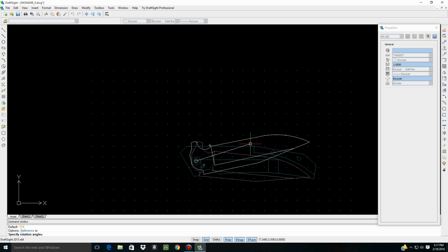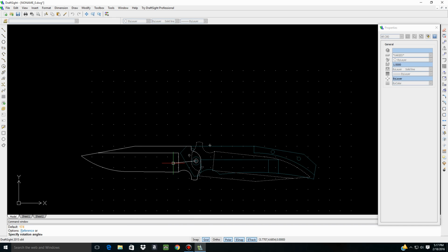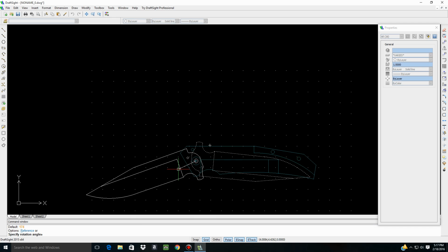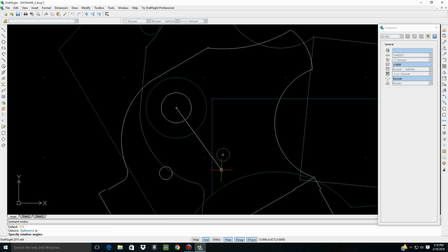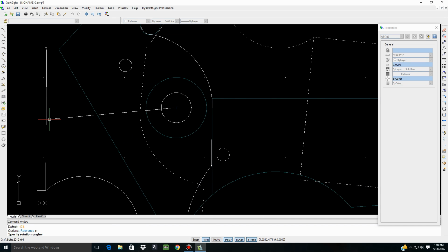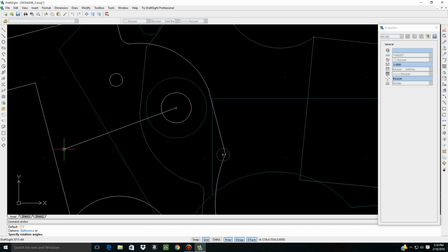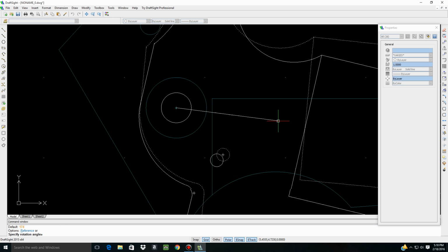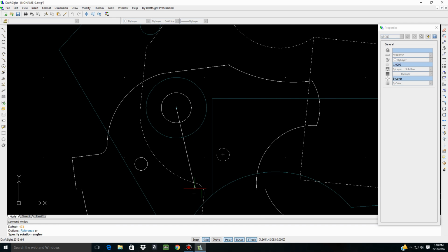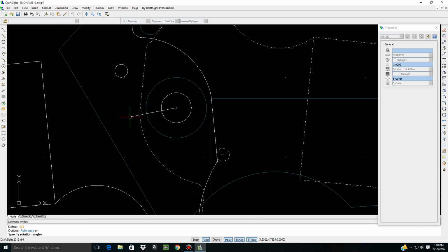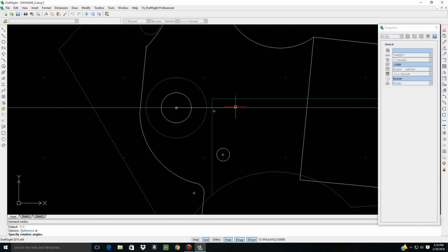You see, we never fall off the blade. This will make for a very smooth knife. So imagine it's open and you go to unlock it. You have to move the blade that much to get the detent ball. Watch right here. Right? So your blade is locked up. You go to unlock it, and boom, your detent ball is already on the blade. So now you're riding on a bearing the whole way, and then you sink in right there. So again, rotate it, boom, right on, and your blade should move freely.